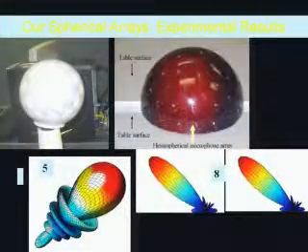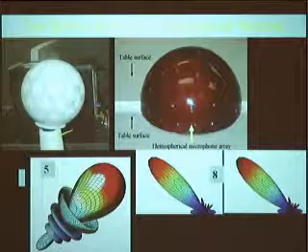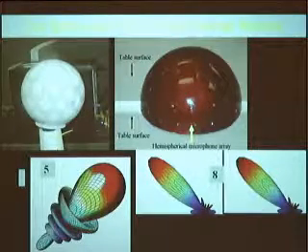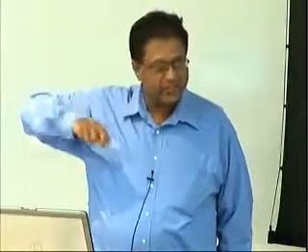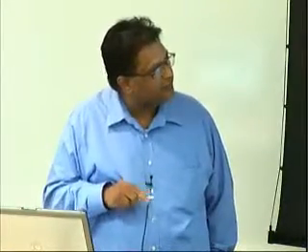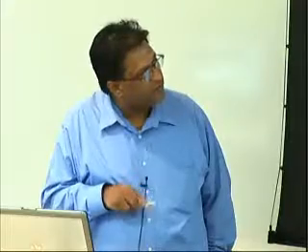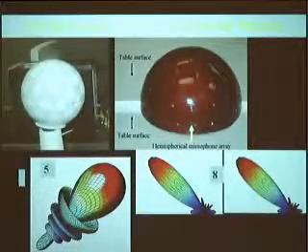So then we proceeded to build different arrays, and these are actual experimental beam patterns obtained with these arrays. This is an order 5 beam pattern. This is a main lobe, and we built also a hemispherical array. This was for a video conferencing application, where we placed the hemisphere on a table, and the sphere is completed by the image of the hemisphere in the surface of the table. So you get, for free, double the number of microphones because of the image principle. And with the same number of microphones, you're able to get much higher order beam patterns. So this is an 8th order beam pattern, which is relatively tight.